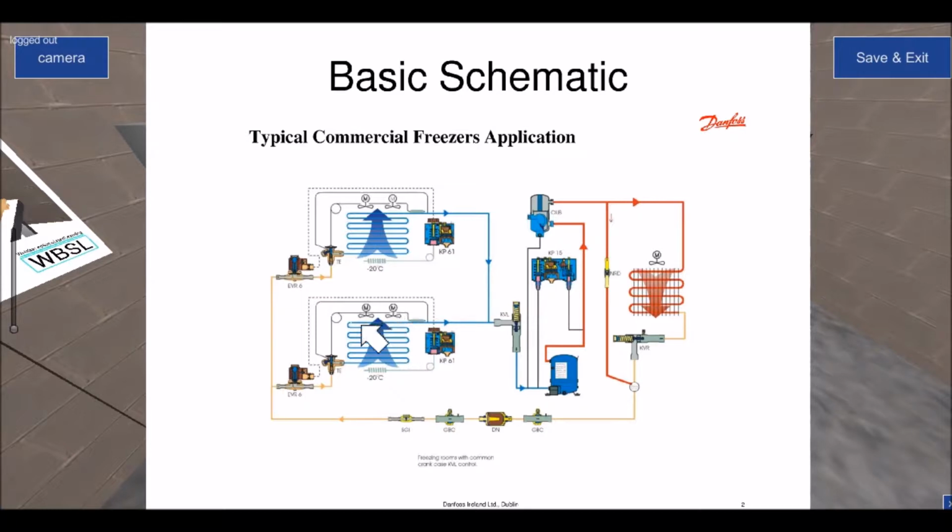More liquid in means that it boils off later in the evaporator, which reduces the area that you have for the superheat zone. And this is what I was saying about the superheat moving between 5 and 8, which is the superheat value, a difference of between 5 and 8. So when you're at 5 degrees, there is less pressure pushing down on the diaphragm, so the valve starts to modulate in the closed position. And when you're at 8 degrees or anywhere in between, there is more pressure pushing down on the diaphragm, so the valve will start to modulate in the open position,